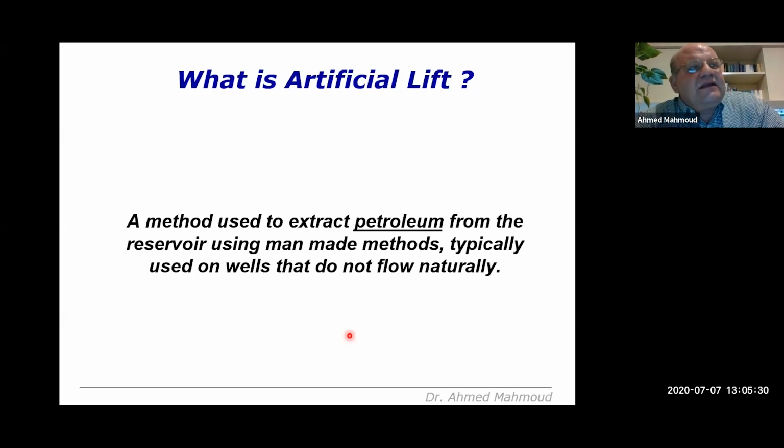However, if you have confirmed data or results, whether it is seismic data, geophysical data, or petrophysical data, that confirms that you do have hydrocarbons in place, and after drilling the well is not flowing naturally, and in some cases during the DST you confirm the existence of hydrocarbon in the reservoir, then the only way to get the well to flow is to add an artificial lift method, which is basically a helping hand for the reservoir to be able to deliver petroleum products, hydrocarbons, to surface.